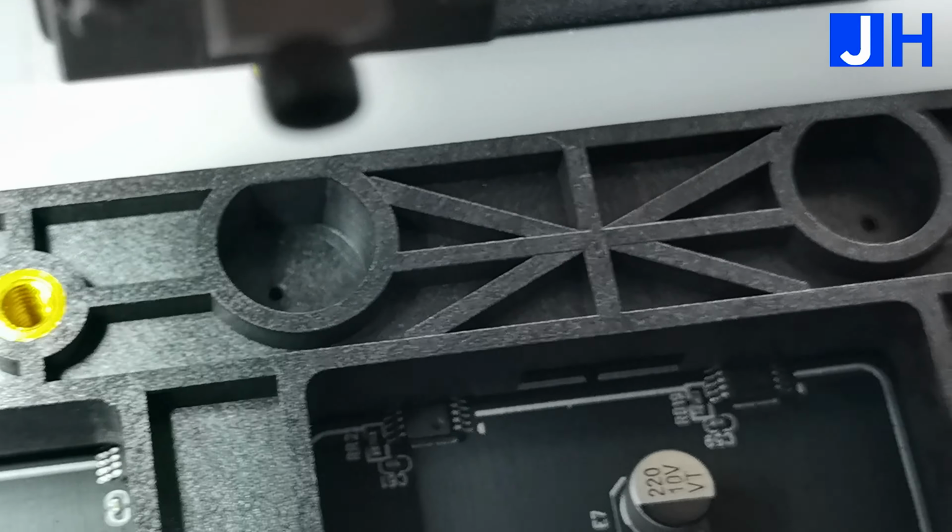Click the navigation button. Find this user run parameters. Select item 9 and click Set Visual Camera Parameters. Click the down button. Change this parameter to Vision Camera. Enter 2 and click OK. When we select the screw hole coordinates and click Move, the CCD camera moves above the screw hole rather than positioning the nozzle above it. Only switch to the screw nozzle when the Z-axis height needs to be detected.